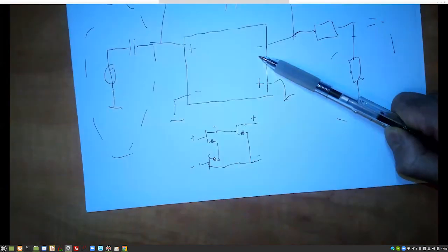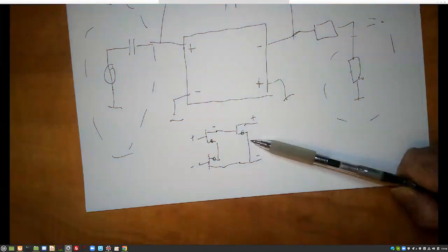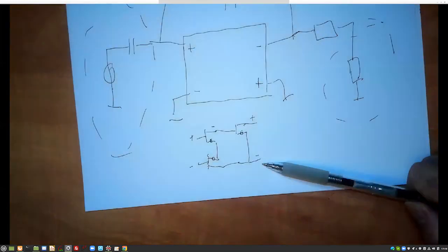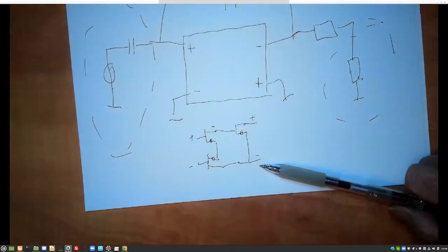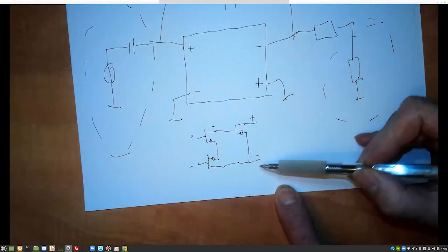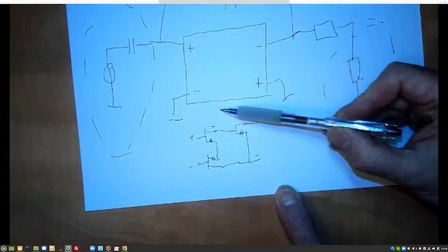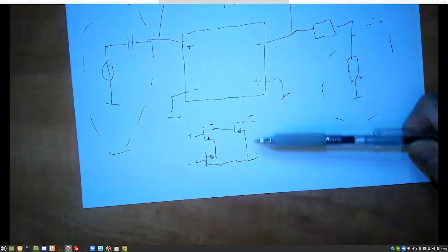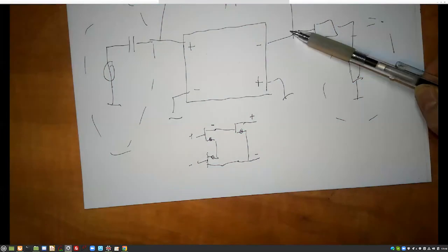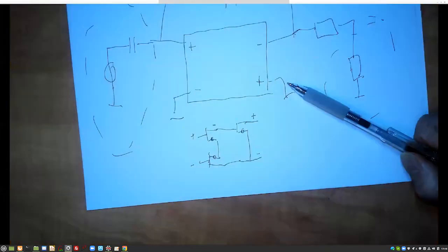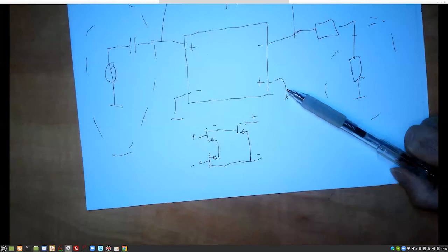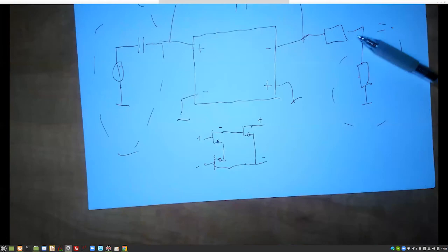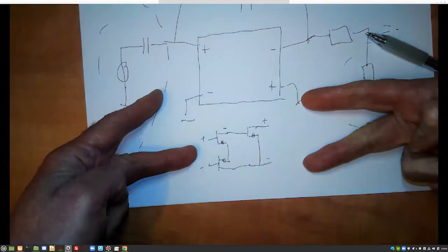In the last case, the source of this one, of the complementary parallel, will be connected to the signal ground, and this will be connected to signal ground, and here will be the feedback capacitance. In the first case, the source will be connected to the load, and the drain will be connected to the ground. This is a nice one. Well, I don't know if it's nice, but let's say it's an option. So we can just flip the whole thing and place it in there.